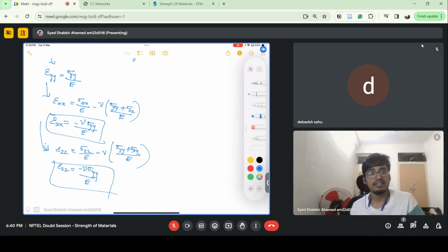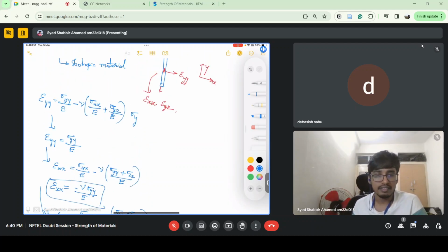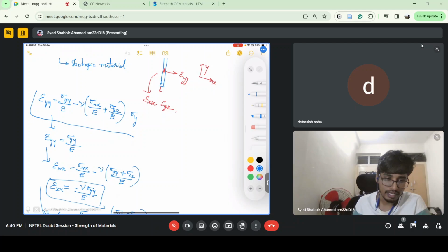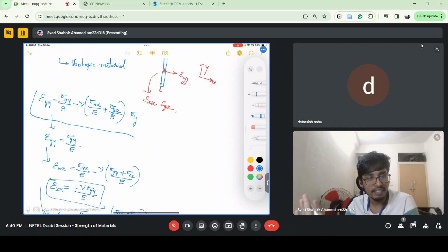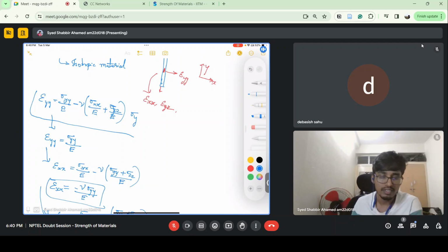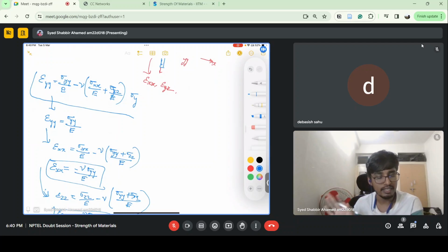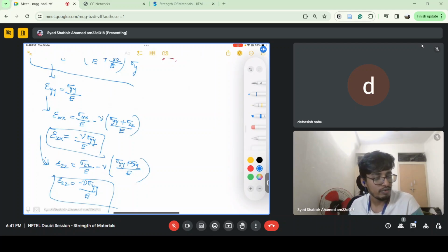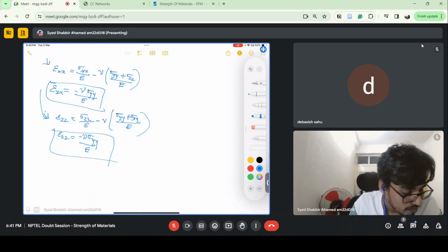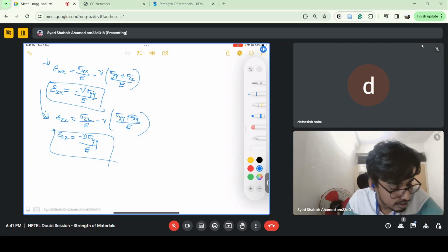Whenever a stress strain relationship is asked anywhere, you have to give this generalized Hooke's law for an isotropic material. You should not say stress is equal to strain into Young's modulus. That is only in the case when the tensile test is being conducted. Given that a tension test is conducted, then you can say sigma yy is equal to E into epsilon yy. But generally, if someone asks you the stress strain relationship, you have to give this generalized form. Then you deduce from it that if this is a tension test, the other stress components are 0, and that's how we get sigma yy by E. We have to make sure these things are taken care of, because people can puzzle you over these things.